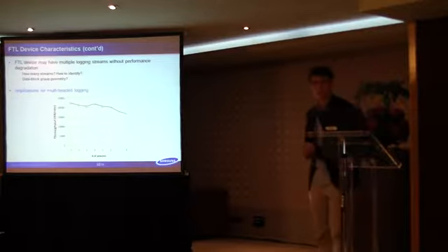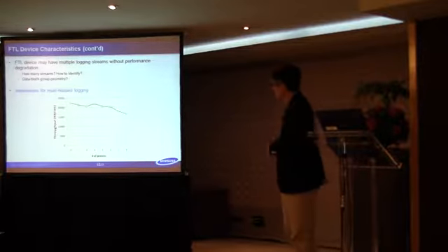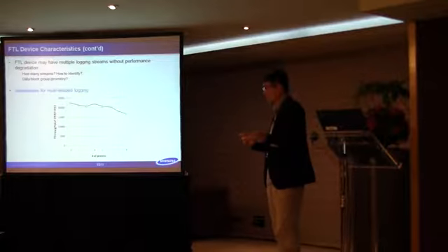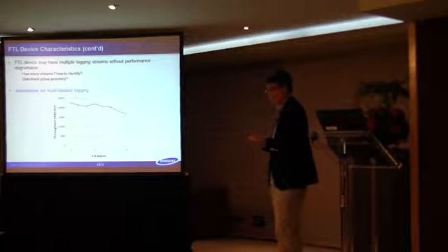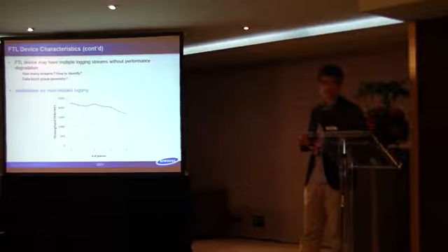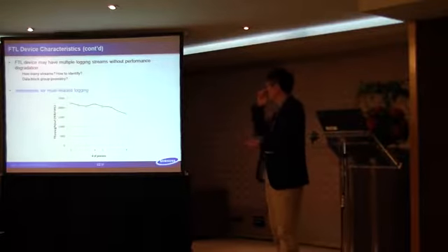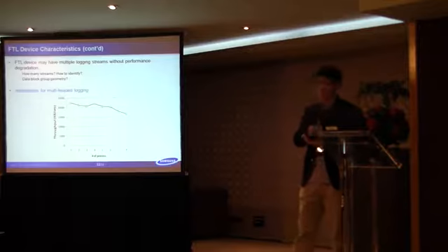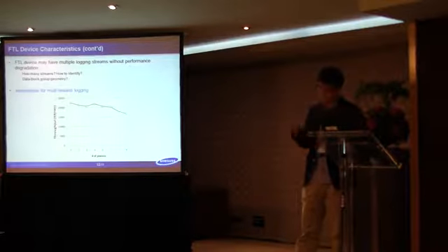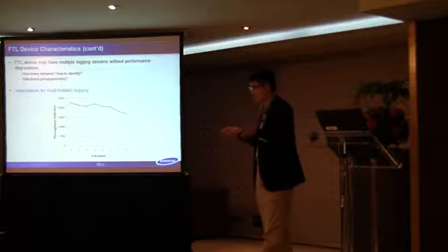And also, the FTL has a very interesting feature, because it has multiple log blocks. As I said before, the hybrid mapping has a log block for each data block group. There are many log blocks for concurrent page programming.